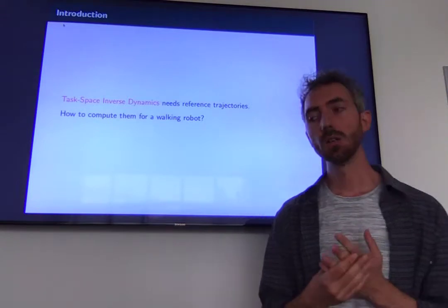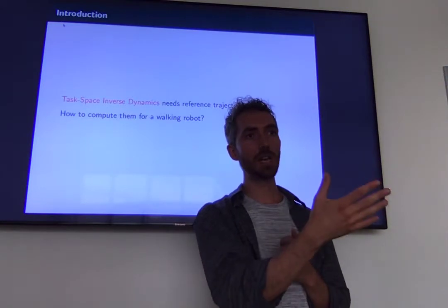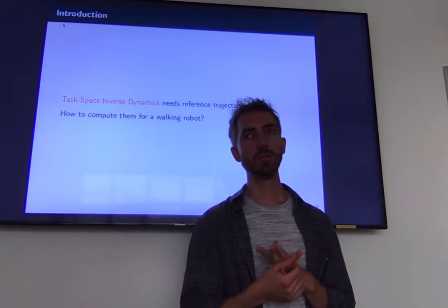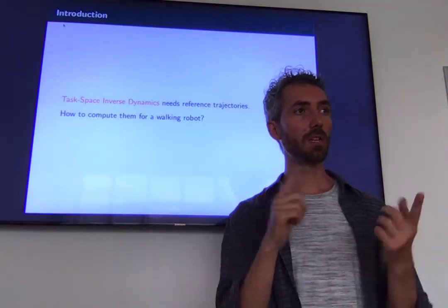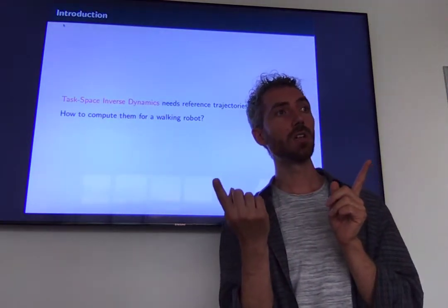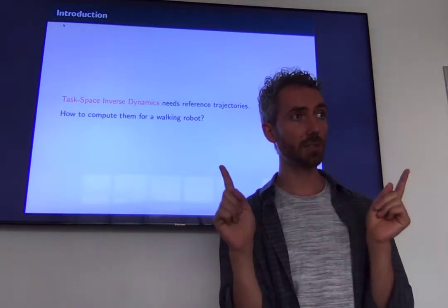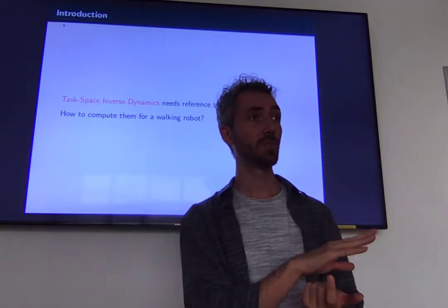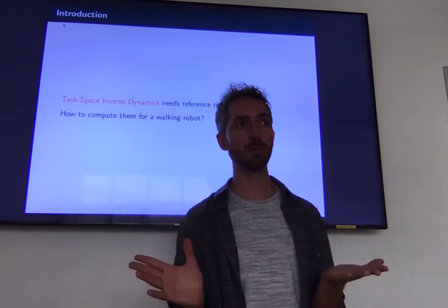That's true. But let's suppose that you're doing trajectory optimization and you're in one of those cases where you also have the control signal. So I'm not sure if this is official, but my explanation of the difference between the two terminologies is that when you're doing optimal control, you're looking for a control policy, which is not just a trajectory, but a function that maps the state to the control, so that you know what to do no matter where you are in your state space.